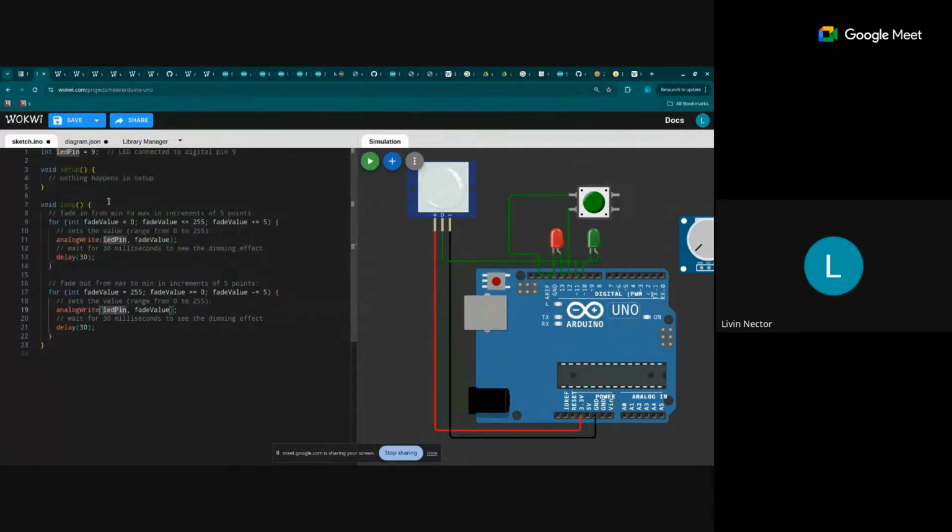Here, as you can see, instead of putting the pin value in every position, they have declared it as a variable. What is the advantage of using that? If you want to change that pin, you don't have to change it everywhere in the code. There is only one place where the configuration is. This is generally considered good practice: setting the pin numbers as a variable or as macros, using #define. So now here we can just change it to 10 for our code. That's the code.